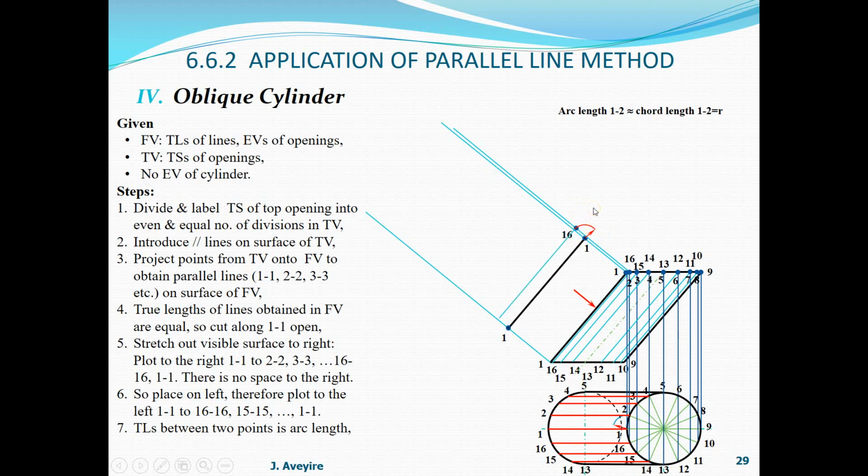Then we draw our line over there and project the 16 line to get the point 16. Likewise here now from the 15 line we get a center here, radius again, and that will give us our point 15. Then we draw our length of line 15, then we get the corresponding 15 point projector over here to locate our point 15.